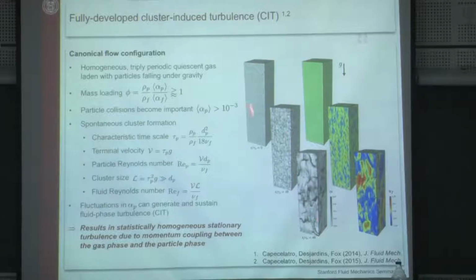The fact is that in this flow, we find clusters, those dense regions, that start emerging on a length scale, and I'll show that it corresponds to this distance traveled upon acceleration, L, which means that effectively the Reynolds number that properly characterizes the agitation in this system is indeed this Reynolds number based on L. So it is a turbulent-like flow field, not classical turbulence in any way though, that is entirely caused by the two-phase system.